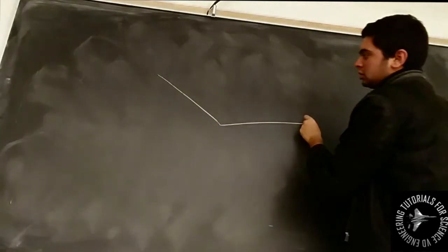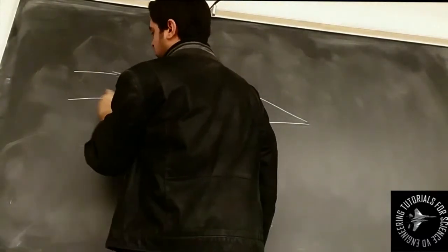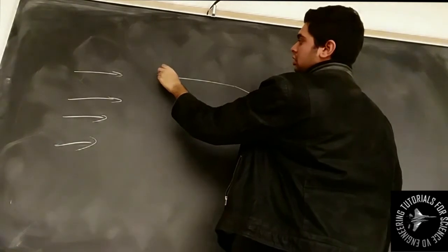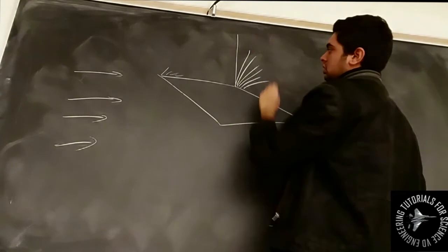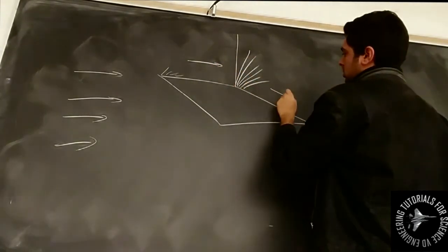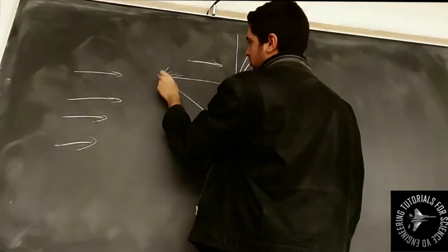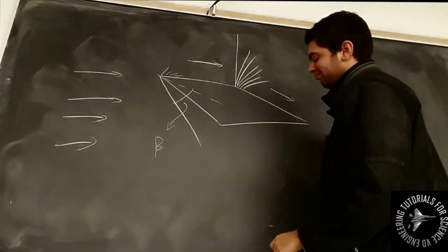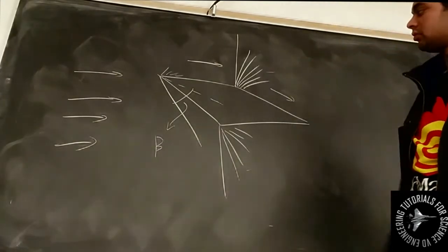So from that, now I will explain what happens in the flow just to give you a better understanding of it. So we have my free stream over there. You have an expansion wave here because the flow is turning a convex corner. And then we have expansion wave at the top because the flow is turning again. So the Mach number will speed up as you go from left to right. Below we have an oblique shock because the angle is steeper, and then we have the concave corner, and then the pressure is expanding over there. And then we have another expansion wave as shown over here.